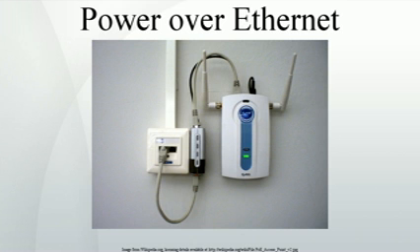There are two types of PSEs, end-spans and mid-spans. End-spans, commonly called PoE switches, are Ethernet switches that include the power over Ethernet transmission circuitry. Mid-spans are power injectors that stand between a regular Ethernet switch and the powered device, injecting power without affecting the data. End-spans are normally used on new installations or when the switch has to be replaced for other reasons, such as moving from 10/100 Mbps to 1 Gbps or adding security protocols, which makes it convenient to add the PoE capability. Mid-spans are used when there is no desire to replace and configure a new Ethernet switch, and only PoE needs to be added to the network.